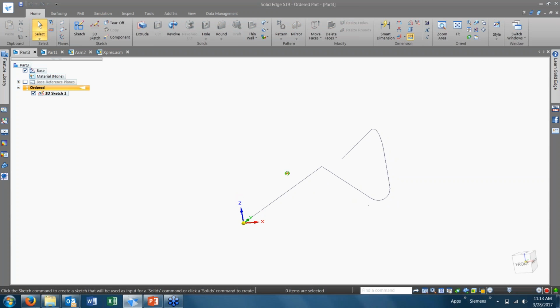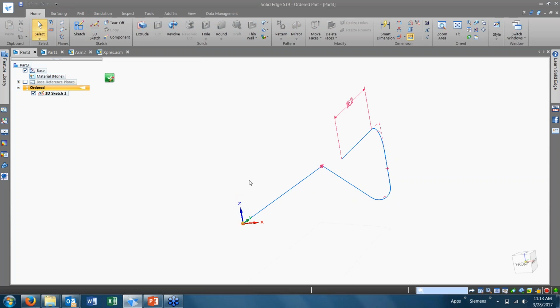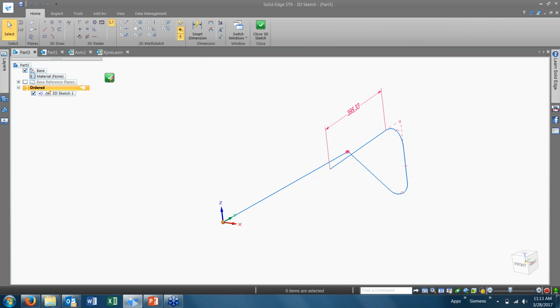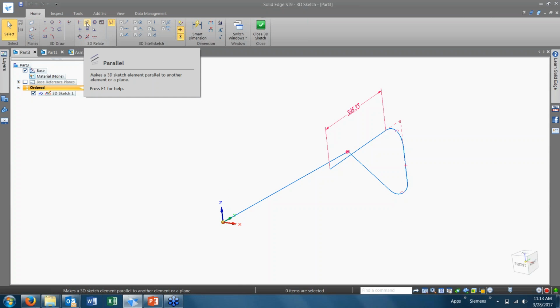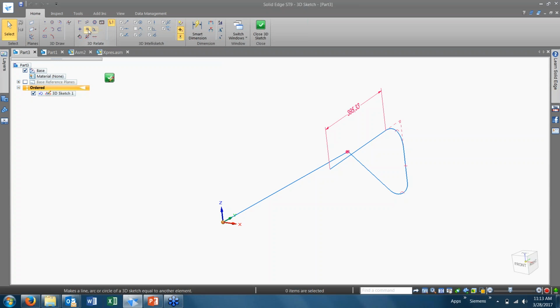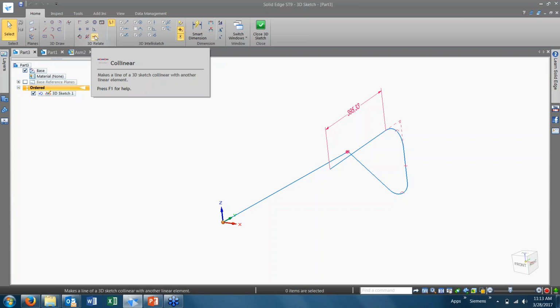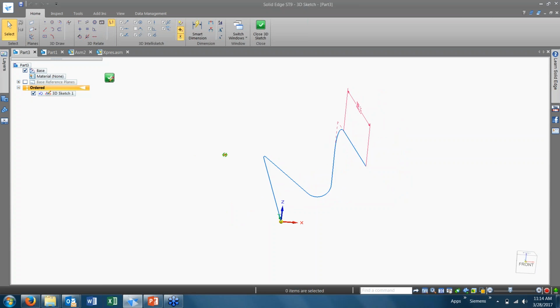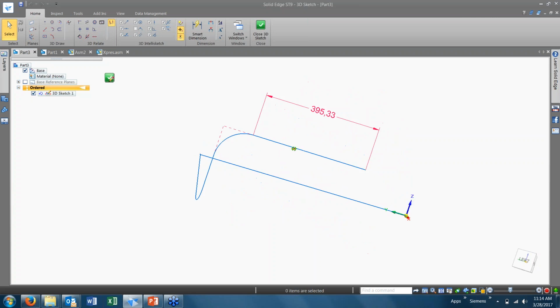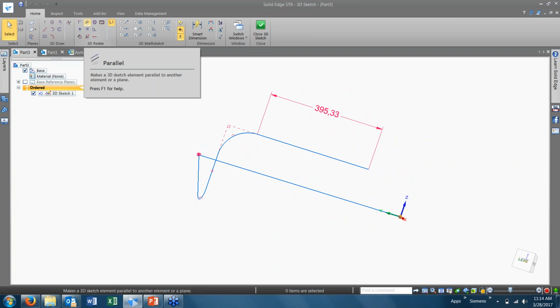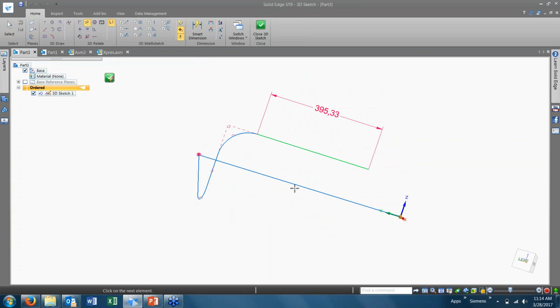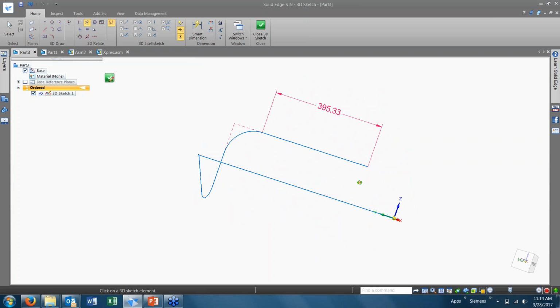Beyond that, for the most part, 3D sketching works very similar to 2D sketching. So making a change to an existing one. Being able to put 3D constraints, such as connecting two lines, making lines parallel or perpendicular, equal length, or being able to use your other constraints such as tangent, horizontal, vertical, concentric, or collinear, just like you would in a two-dimensional sketch. So here we have an example. I can come and grab the parallel and choose these two lines to define those as a parallel relationship.